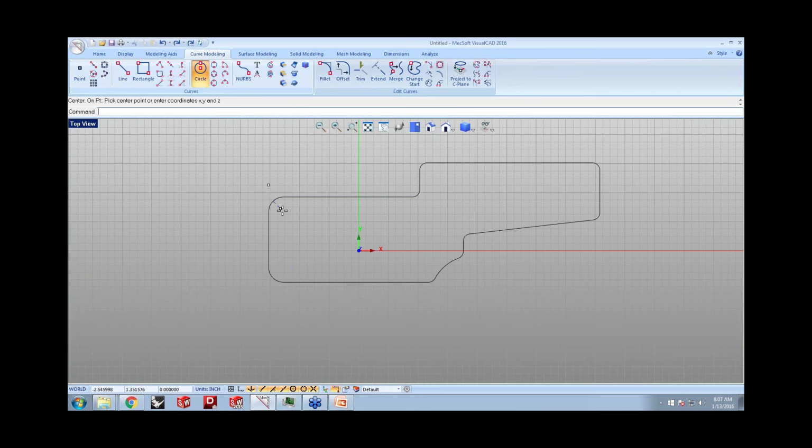I'm also going to go ahead and put some holes in here, and with the help of the visual aids enabled, you'll notice that it automatically gives me indicators to snap to specific areas, and I can specify the diameter for these holes. With the continuous command recall turned on, the command automatically stays active in here, and I can keep creating geometries wherever I need them to be.